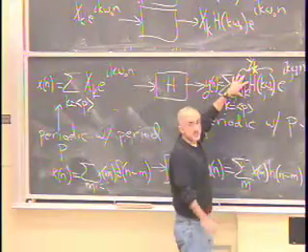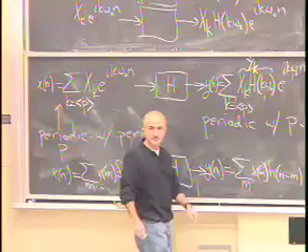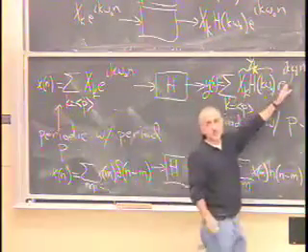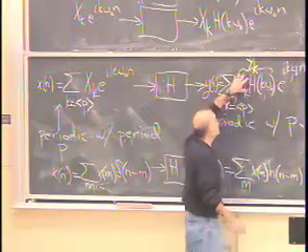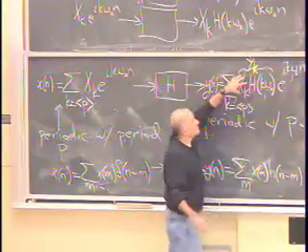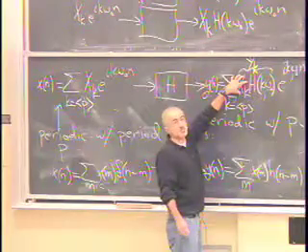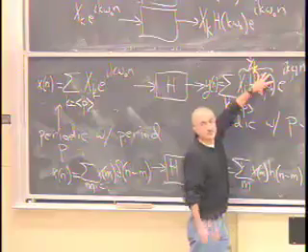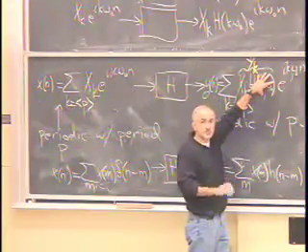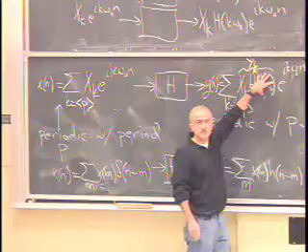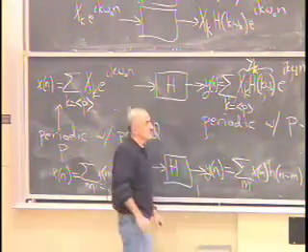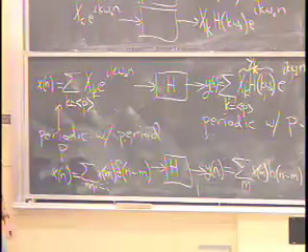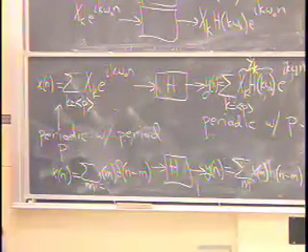If xk happens to be 0, it means it just doesn't exist in your input signal. So no matter what the filter does, it's not going to suddenly pop up in the output. And if this particular frequency happened to exist in the input signal and had a contribution to the signal according to the magnitude of this xk, then the filter may amplify it further or attenuate it, just like an audio equalizer would. So these are partial reasons why we decompose signals into harmonics, or more generally, into complex exponentials.